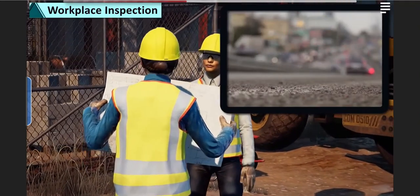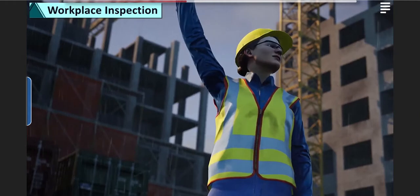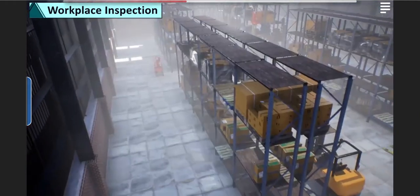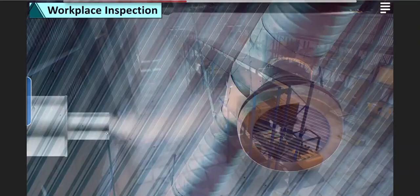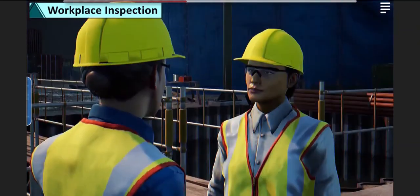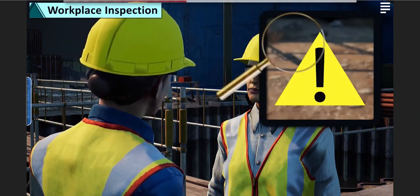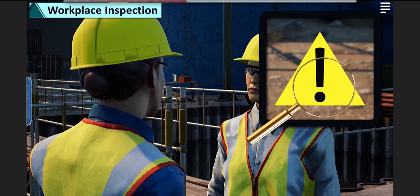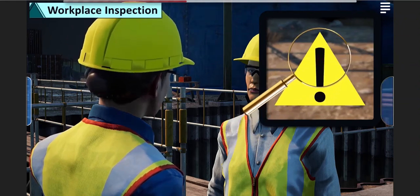The operator must also check for the presence or development of hazardous locations, atmospheres, and conditions, including wind and weather conditions. This includes hazards created by operating MEWPs in enclosed spaces and the need for proper ventilation. If potential hazards are identified during the operator's workplace inspection, which are not accounted for in the safe work plan, the operator must notify their supervisor and must avoid the hazard until it is addressed.